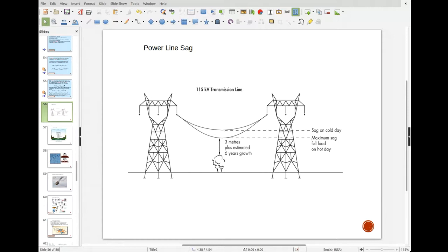At such a high voltage, you can get a current to flow through that wood. Now, if a tree was to reach that wire, it would not short it out. It would act like another resistance, because trees are wood, so they're not like metal. They're not conductors. They're more like insulators, but you can get current to flow through an insulator with a high enough voltage. And so it looks like another big resistor there.